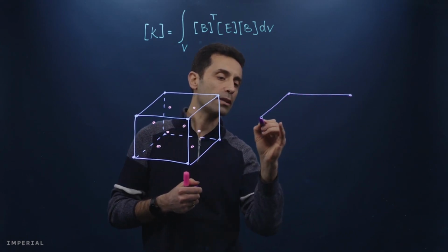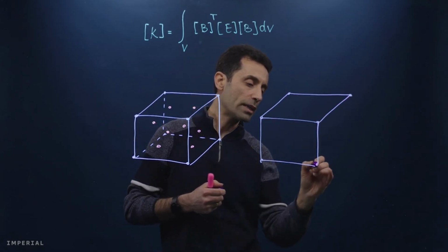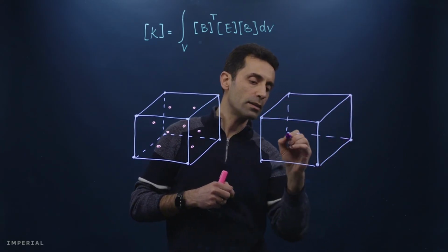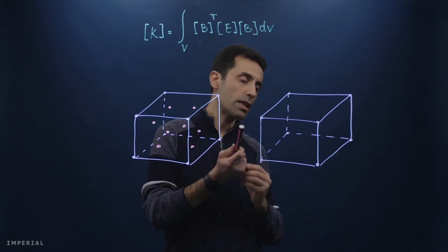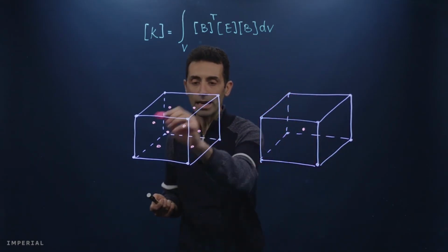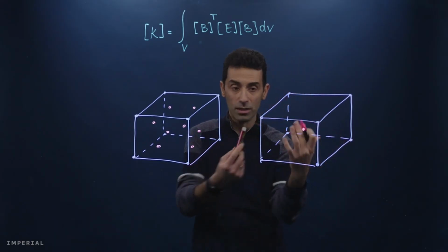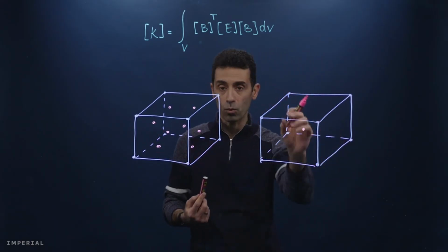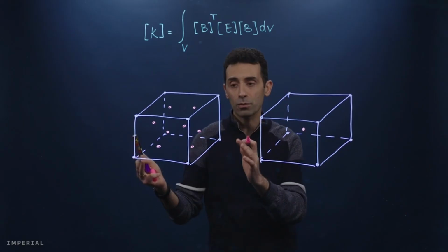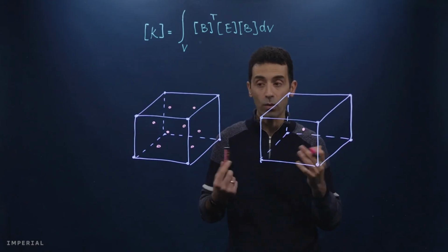So what I mean is that instead of using those 8 integration points, we can evaluate that integral by using a single integration point, which of course is located at the center of our hexahedral element. This means that computationally this is much faster, we just evaluate in 1 point rather than 8 integration points. And then we can also eliminate those problems with nearly incompressible materials, instability, and over stiffness.